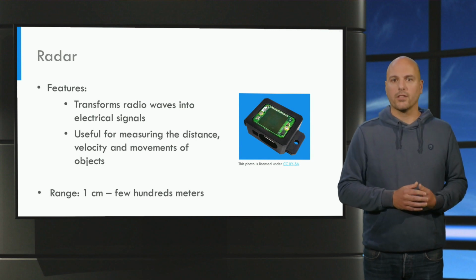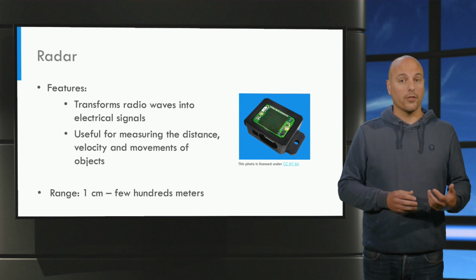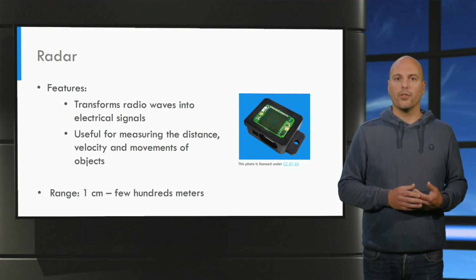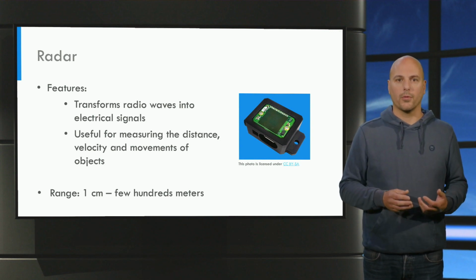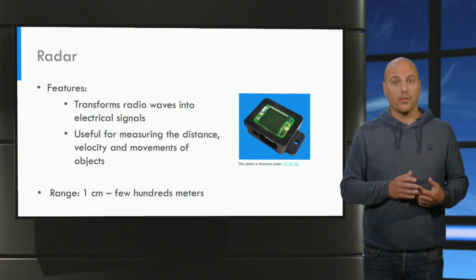More complex radars might use frequency modulation in order to detect range and Doppler continuously, so without sending a pulse. They might also use phased arrays, multiple radars with a phase shifter to steer the radar beam without the need to physically turn around.